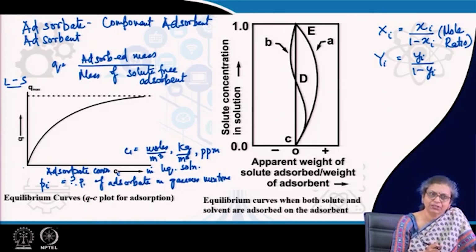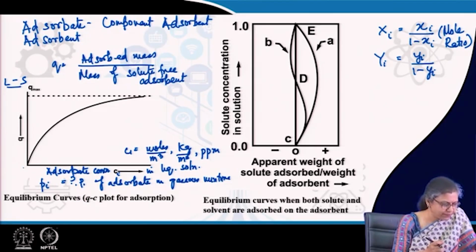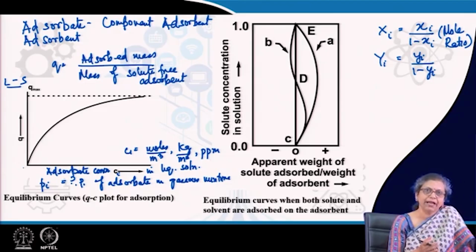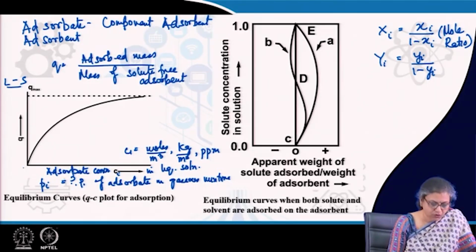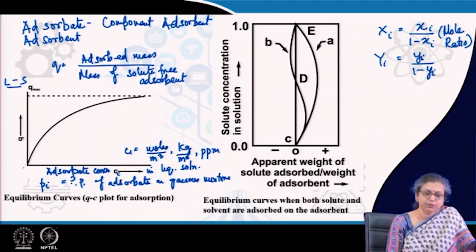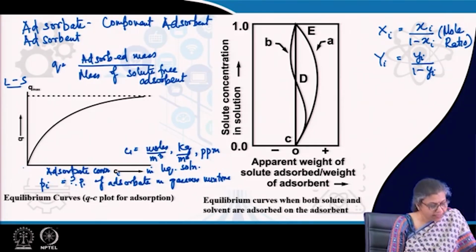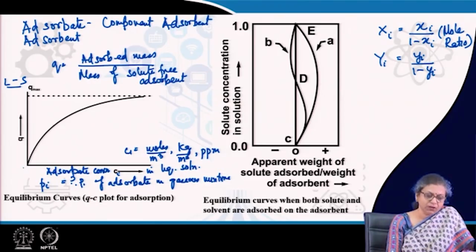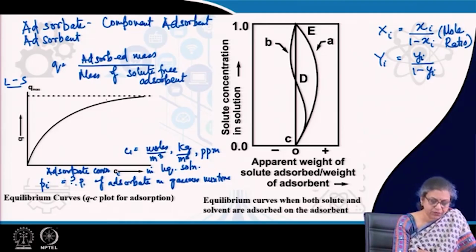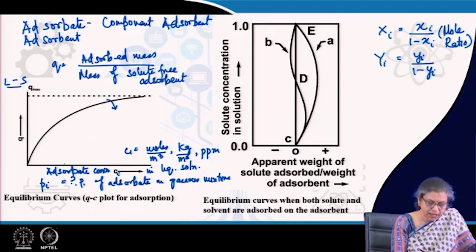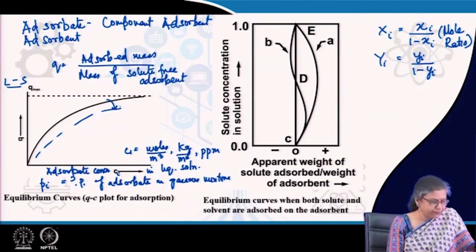As we go to higher temperature, adsorption decreases, right, or rather the adsorbate loading at the constant solute partial pressure for gas adsorption, and also at a constant concentration of the solute in a liquid solution, the adsorbate loading or Q decreases, right. So, with increase in temperature we find that Q decreases at a constant P, and we get something of this sort, right.